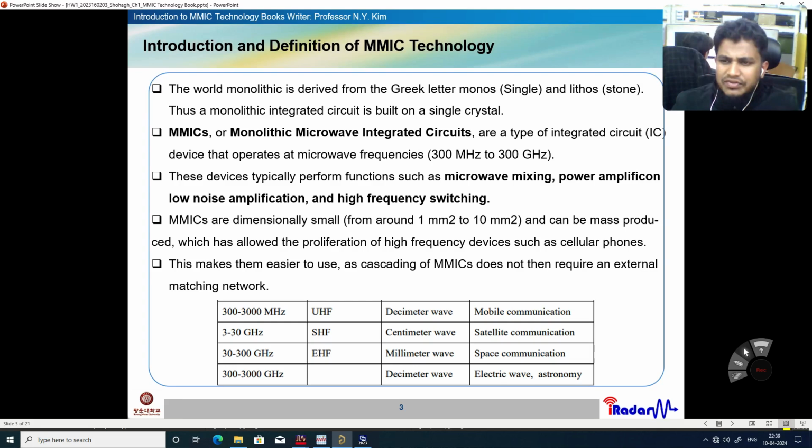There are three types of circuit elements that either are used in chip form or are fabricated in MIC. First, distributed transmission lines: we know microstrip line, coplanar waveguide line, and strip line. Another one is lumped elements, that is resistance, inductance and capacitance. The last one is solid state devices, which are more important in our MMIC technology, that is FET, BJT, diodes and transistors.